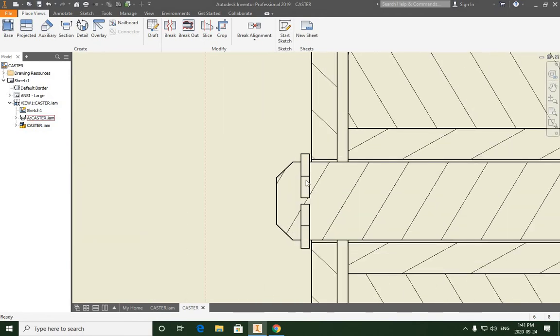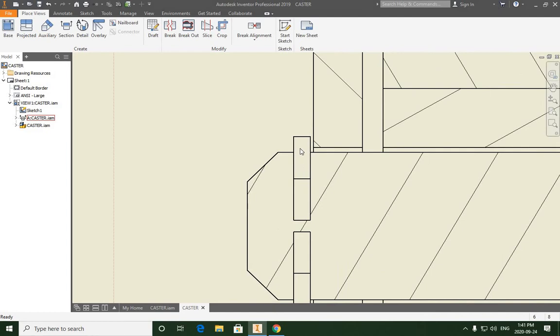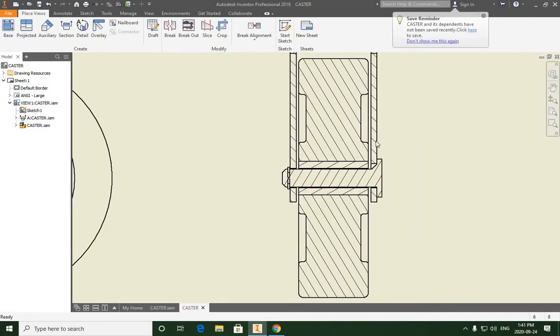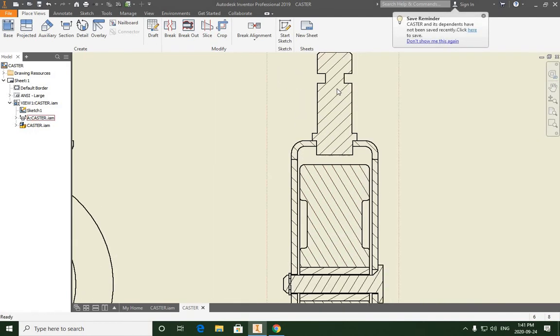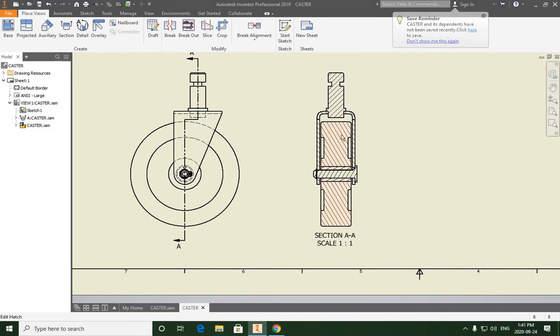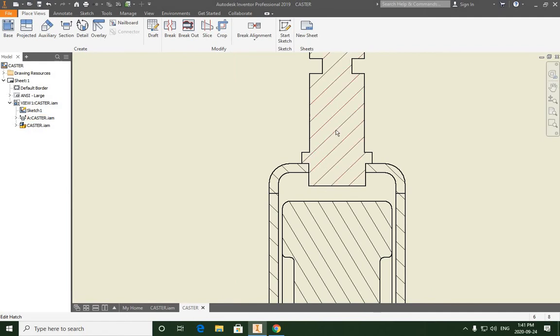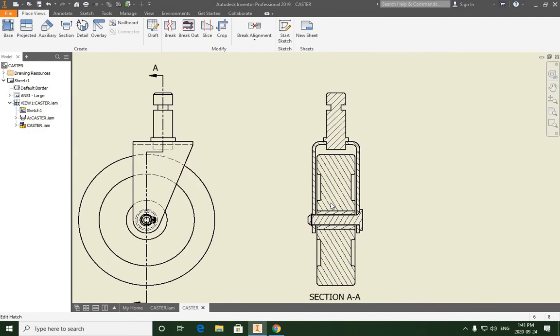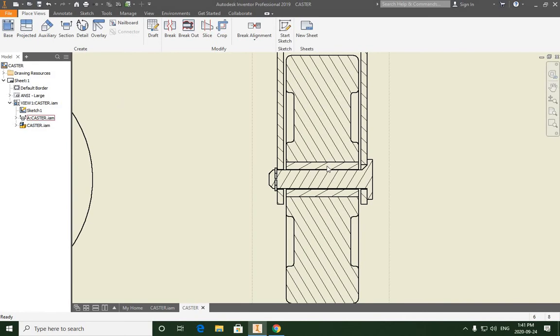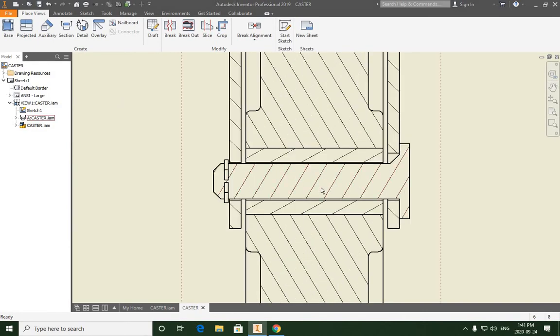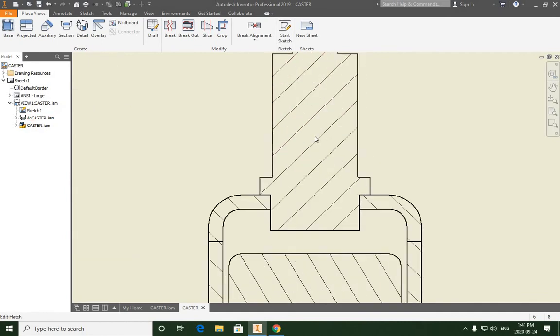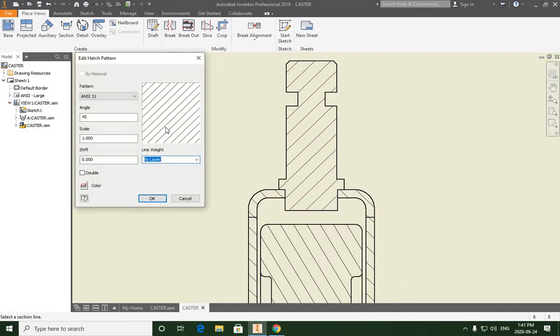We also see that retaining clip attached to that groove diameter, which keeps this shaft from popping out. We have our bracket and we have our post up here. So everything looks great. The only thing I don't like about this is that these section lines, I would adjust these section lines to change their angles a bit. So when we look at this, for example, our post here, we'll start here. That should be an angle of 45 degrees, which it is. All right, so we're going to leave that one alone.